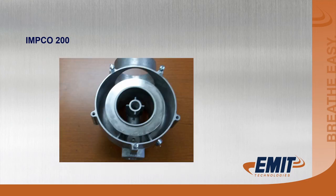Carburetors, IMCO 200 carburetor, one of the things you want to look for is wear points. They wear on these flutes in here. There'll be a little shoulder worn in where the diaphragm and air gas valve assembly have been rubbing. They'll wear off on these. This one will be worn the most because the flow of the air is this direction and pushes the diaphragm over. Always check and see, put your finger in there and see if you can feel a little lip in there.